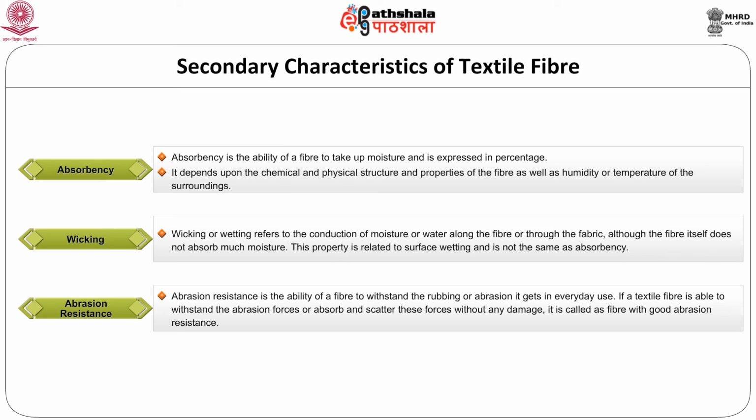Inherent toughness, natural pliability and smooth filament surface are fiber characteristics that contribute to abrasion resistance. A rigid and brittle fiber always shows poorer resistance than a toughened, more plastic fiber. Dyes and finishes used in textiles affect the abrasion resistance.